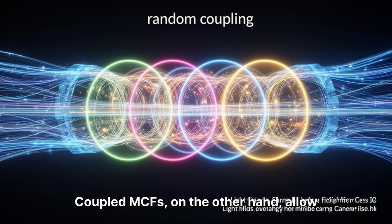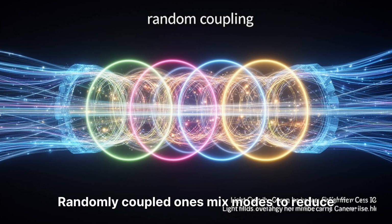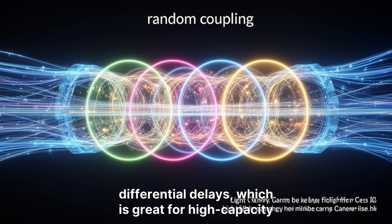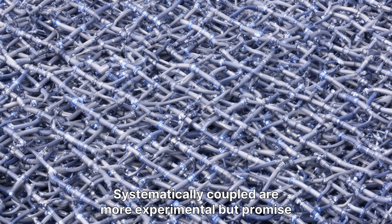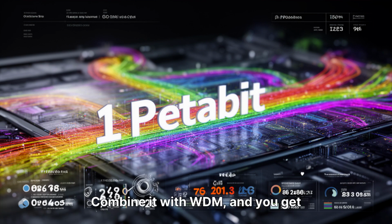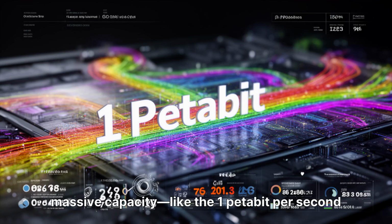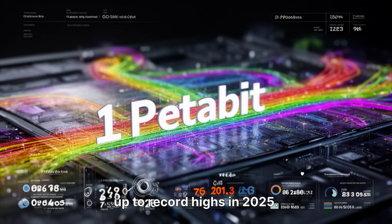Coupled MCFs, on the other hand, allow intentional interaction. Randomly coupled ones mix modes to reduce differential delays, which is great for high-capacity submarine cables. Systematically coupled are more experimental, but promise even higher densities by treating the entire fiber as one superchannel. SDM ties it all together across these spatial paths. Combine it with WDM and you get massive capacity, like the 1 petabit per second over 7-core fiber demoed in 2024, scaling up to record highs in 2025.